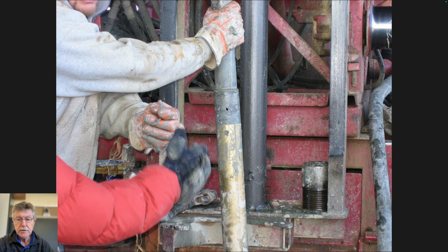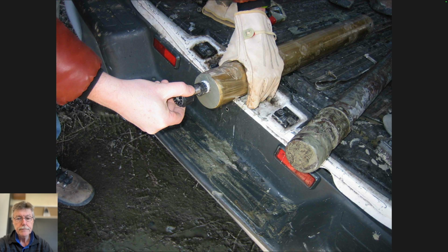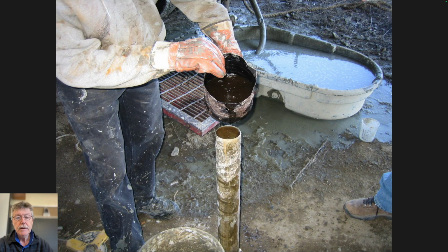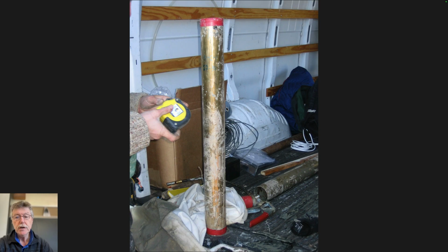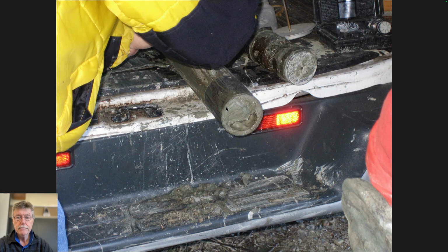This is the coupling of the Shelby tube on top of the component. So this is the tube as it comes out. This is measuring its strength on the end after it's come out. This is the package. This is a tiger torch melting some wax. This is pouring the wax into the top because you want to preserve its nice pristine conditions, same water content, moisture content. And then caps put on the top of it to preserve it. So, yeah. Don't spill it on your hands.